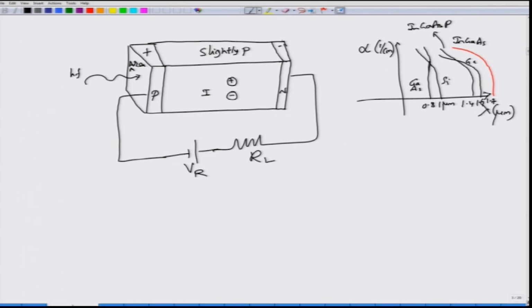What is interesting about these materials is that each of them has a large absorption. On the y axis we have plotted the absorption coefficient in 1 per centimeter, and on the x axis is the wavelength. If you look at this absorption coefficient, it is actually pretty large. For example, for silicon, which I am showing over here, you can see my pen movement there, the absorption coefficient is pretty large, and then at a certain value of the wavelength it abruptly drops down to 0. The same characteristic you can observe for any of the materials.